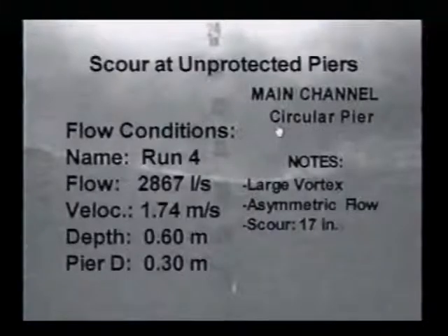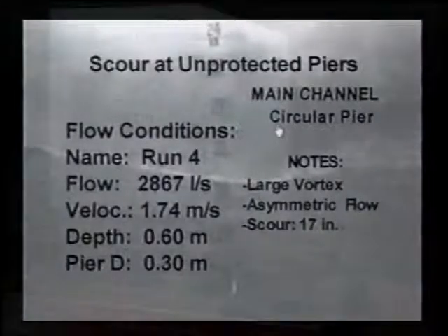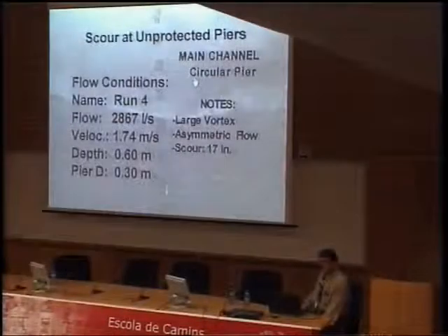And as far as I know, there is no standard sediment transport relation that has any hope of predicting this. There are 3 factors that make it different. One is the pressure field is strongly non-hydrostatic, and our standard formulation for sediment transport is based on hydrostatic flow. And second, the flow contains a collapsing face that is higher than the angle of repose, and third, it contains large discrete eddies which can move sediment out of the system.